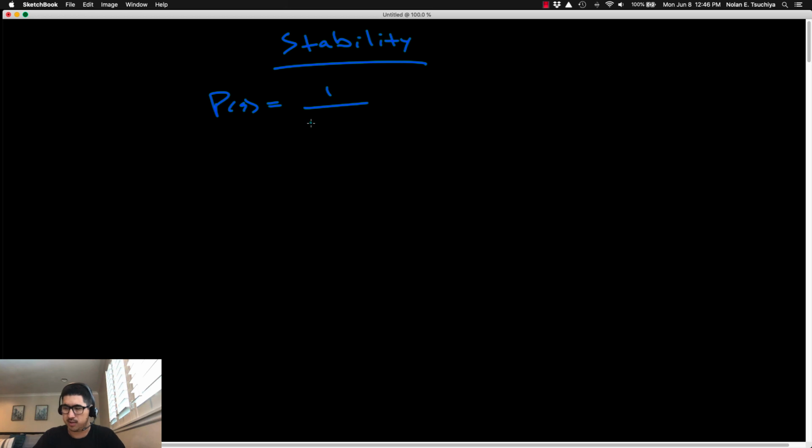If you just look at this example of a first order transfer function, remember our discussion of poles and zeros. For this example, there are no zeros, in other words, there are no values of s that would make the numerator equal to 0. For the poles, there's one. There's a pole at s equals minus sigma.